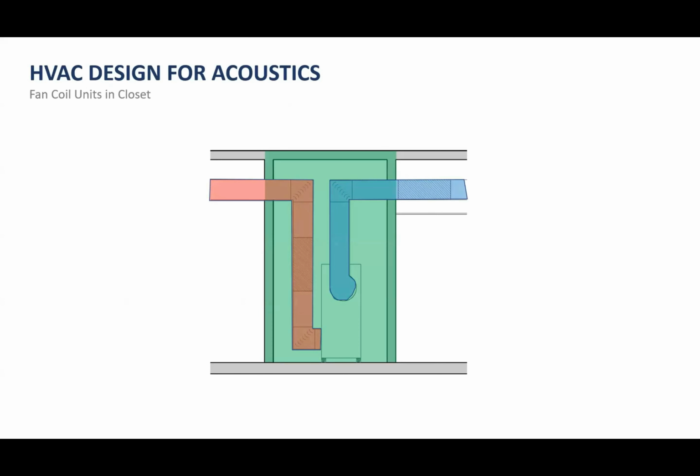Now within those ducts, if this is a loud unit, and it doesn't even have to be really loud to see this, we're probably going to look at adding silencers. So duct silencers will help us control the sound level coming out of these. And as we were saying, vibration isolation is important, so we're looking at spring isolators on this unit to help stop that. So all of these things go into account. The silencers may be a little shorter or longer, depending upon how noisy the equipment itself is.